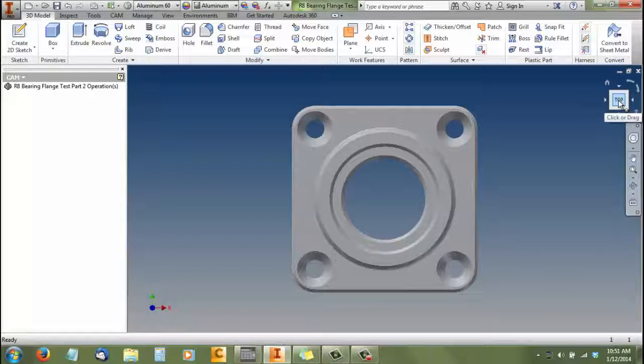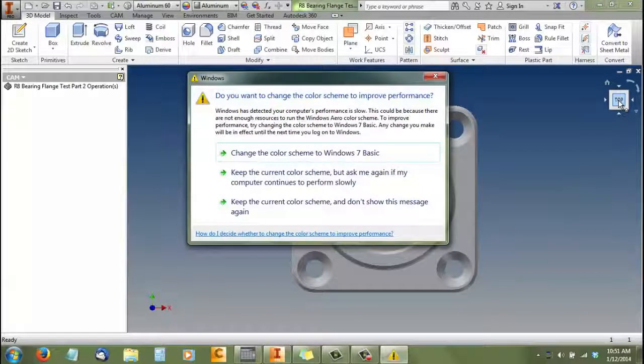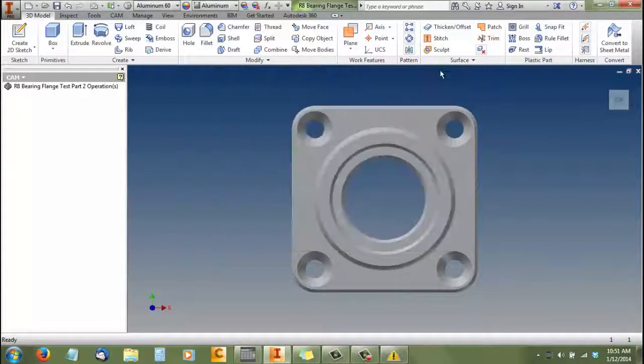We're going to define our coordinate system at the bottom corner of the stock. The reason we do it there is that on the machine, we set the coordinate system right on the corner that we orient the stock to each time we put stock into the machine. That way the coordinate system is actually attached to the vise, and it doesn't move from part to part. So you only have to define the coordinate system once, and that just makes your life a lot easier.